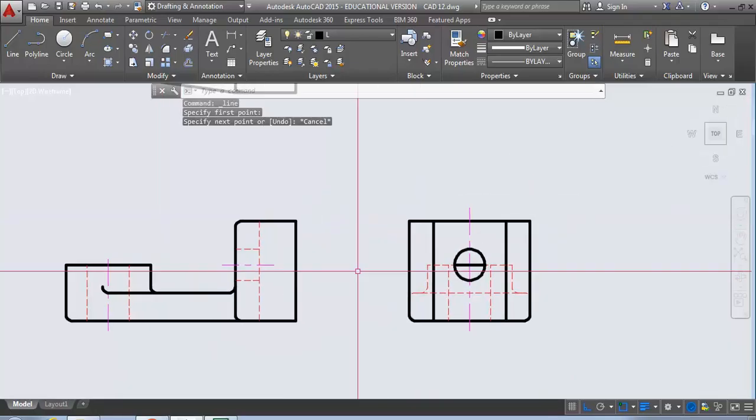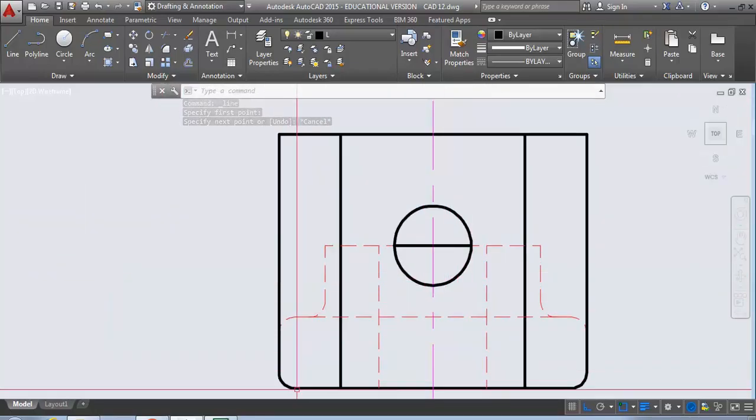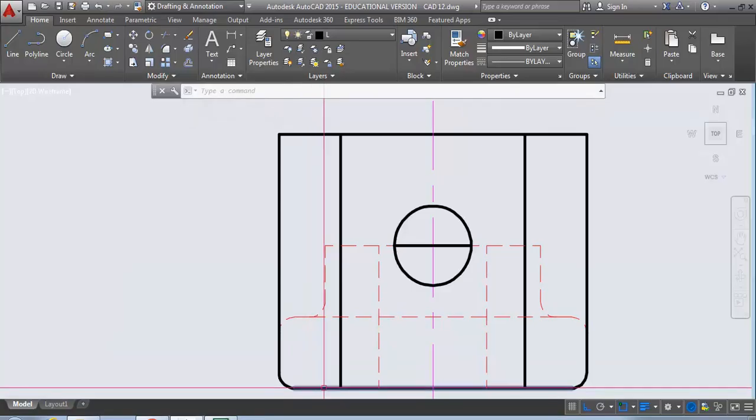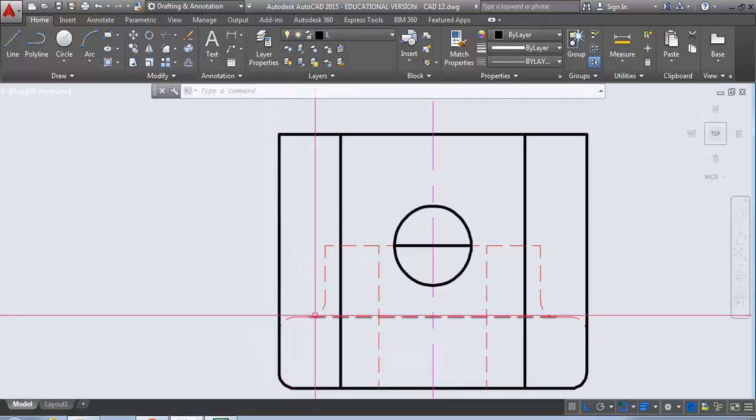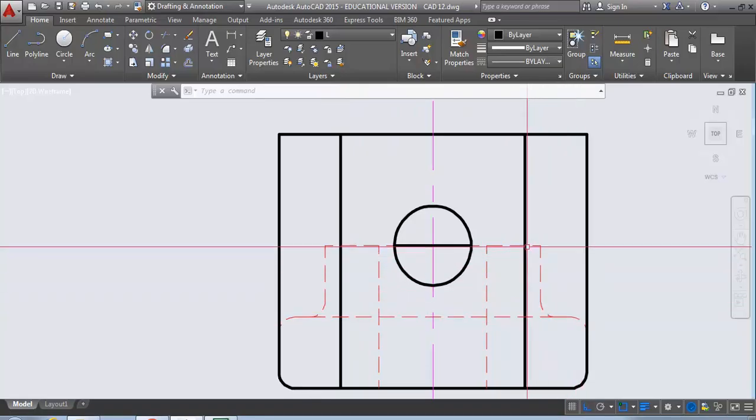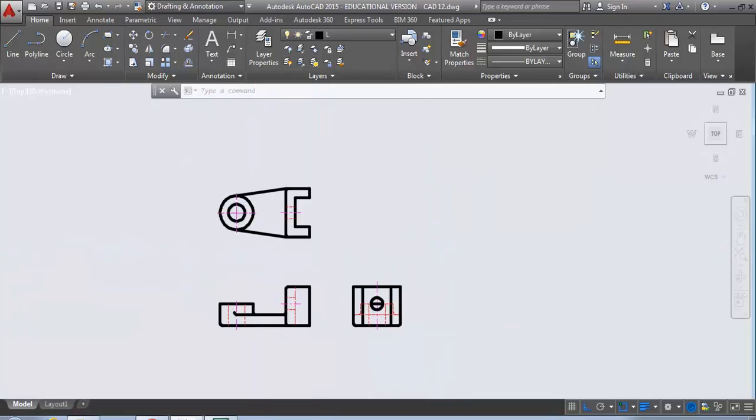And then the right side view is the right side view. Look at the parts that are not machined. If they're not machined, that means they have a fillet on them. So there's a radius there, there's a radius in there. And the same thing on the other side, it is flat at the top. So there you go. There's your three views.